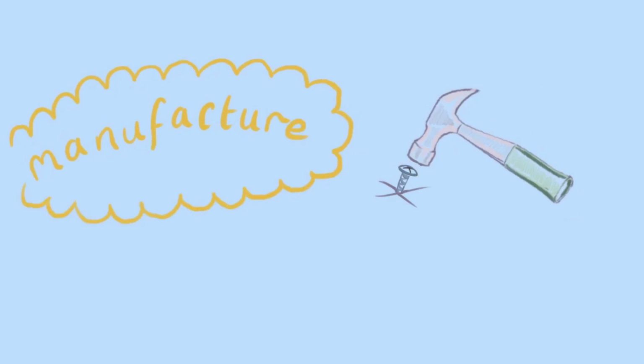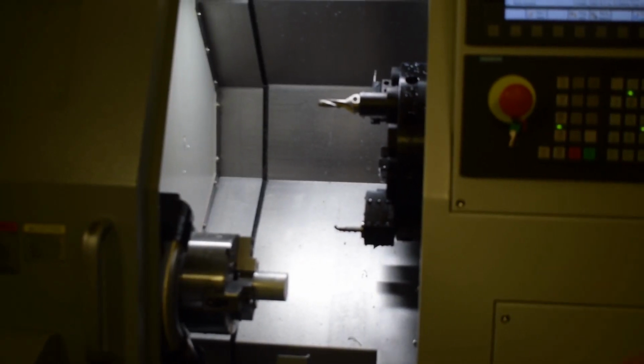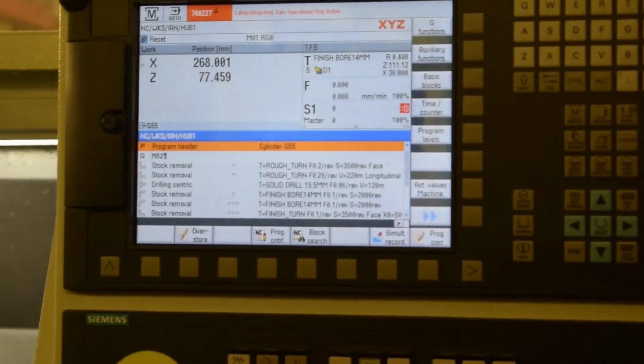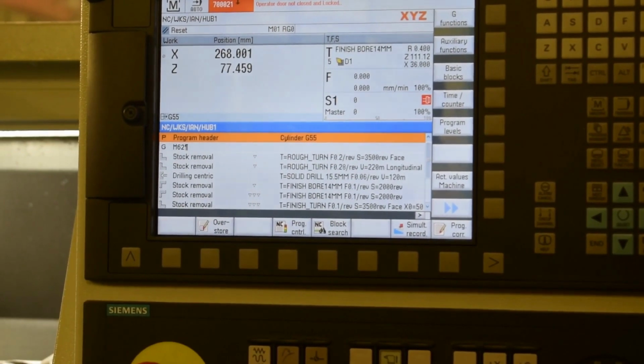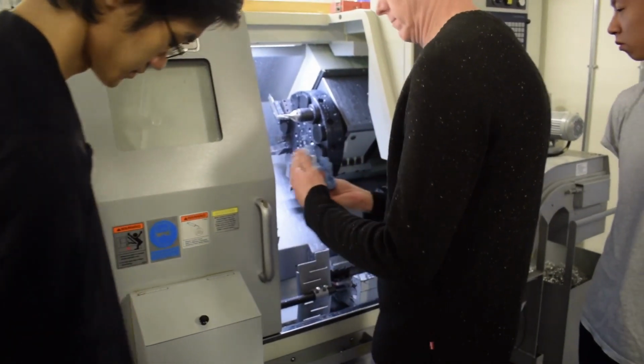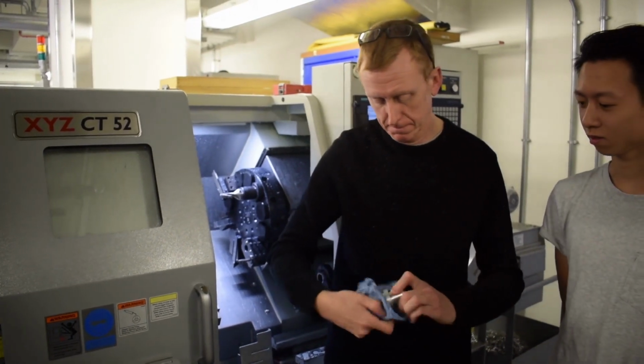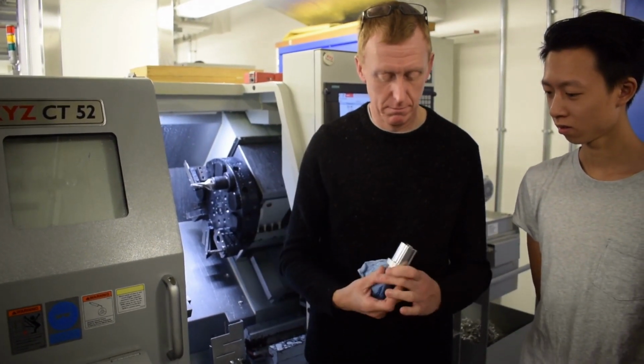To manufacture our turbine, we first started with the hub. An aluminium workpiece was placed into a CNC lathe, and G-code to form this piece into a cylinder with the required dimensions was uploaded to the machine. The result after turning was a cylindrical piece, with a hole in the centre to eventually become the keyway for attaching to the testing rig. Using a CNC lathe increases the accuracy of the job, as human error in tooling is removed.